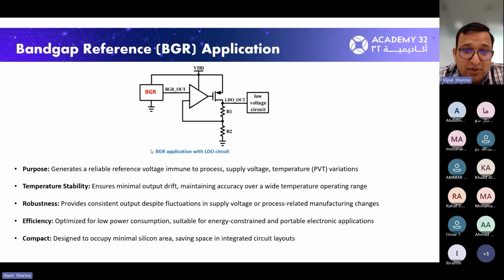And again, the next one is process. By process, I mean during fabrication, all the procedures which are taking place inside the fab are called process steps. Although the control of fabrication processes is very stringent, like the foundries ensure whatever processing is happening on different wafers and different lots is consistent, there is not much variation. But still, since we are talking about dimensions in micrometers and nanometers, even a small change in process or in the property of a chemical or material used in manufacturing can have an effect on the feature size of a layer which is getting developed on a wafer.